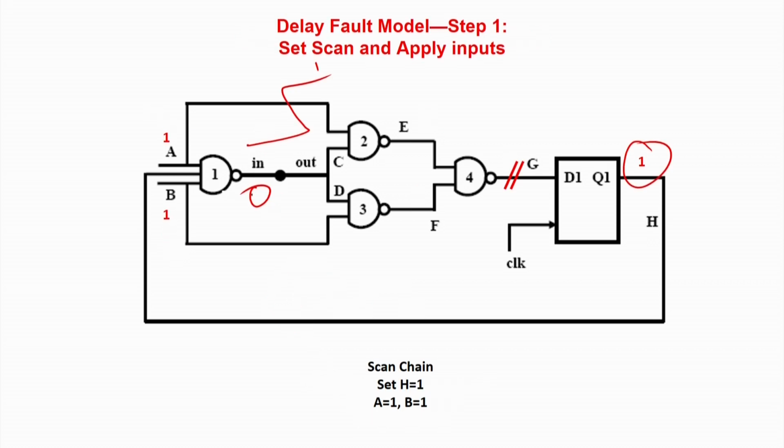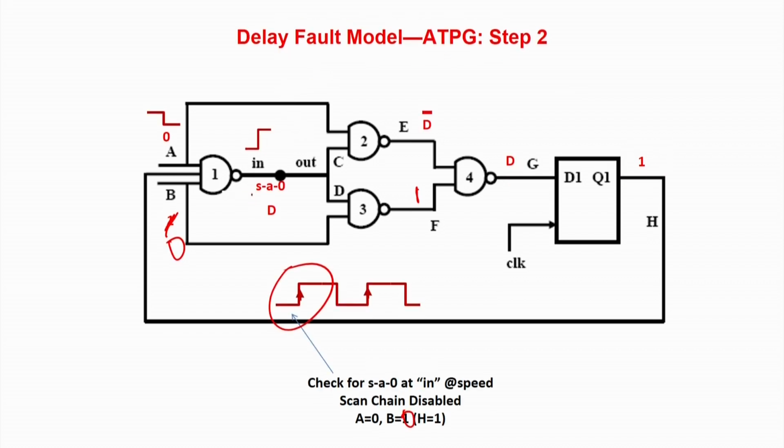So in this case, if this is 0, then I have to make A equal to B equal to 0. But in fact, this B may not be at speed. That is the idea, because generally when I am testing for the propagation of this path, the B going from 1 to 0 can be made in a slow pattern. Mainly I am trying to hit this circuit on this part, because I am assuming that this is the path being followed for the at-speed testing.